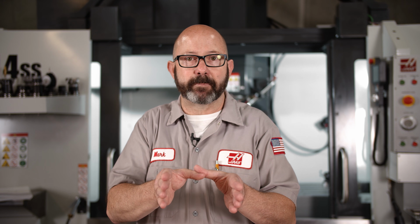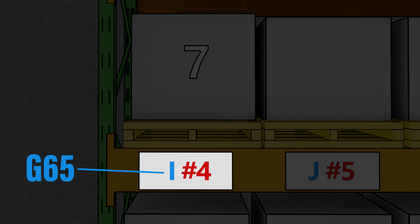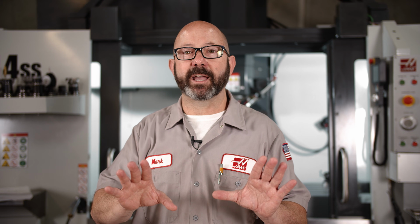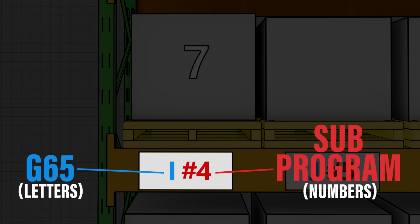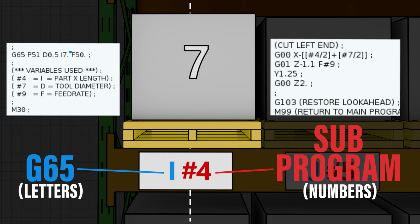Now, each one of these spots on our shelf has 2 different names. It has one name that's used by our G65 and a completely different name, a number actually, that's used by our subprogram. On the main side of our program, our G65, everything is an alphabetical letter. But on the subprogram side, it's a number. In this case, our G65 I value, that spot I, has a number. It's number 4, pound 4. In our main program, G65 I4 delivers the information to the shelf. In our subprogram, we make use of that information by calling up pound 4. It's the same spot, two-step process.